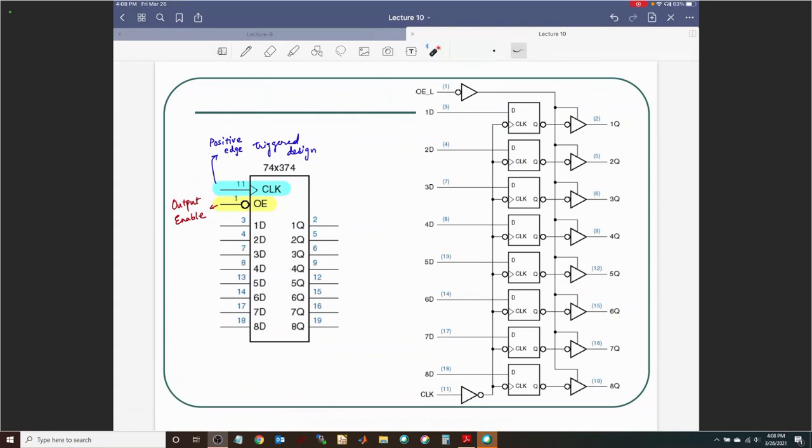Now, you guys remember where we used the output enable signal earlier? In what discussion did we see OE? Cascading. How about we say connecting multiple things together in the context of tri-state buffers, right? That's where we used the output enable. It was selectively putting the outputs in the high impedance state. It was when we were trying to share multiple outputs on the same line. That's where we are going to use that output enable even here.